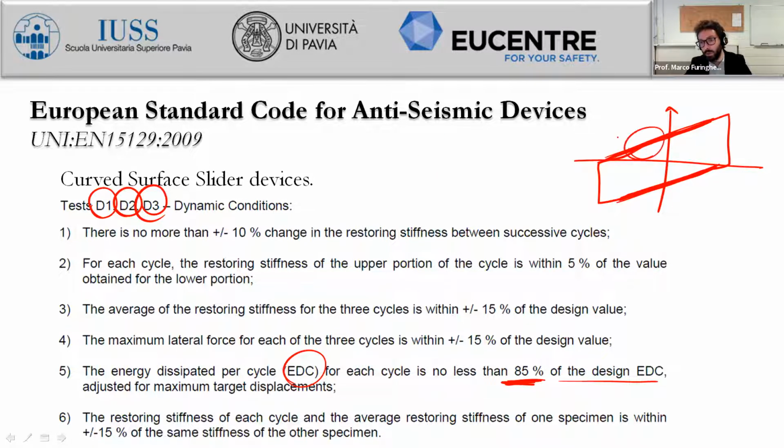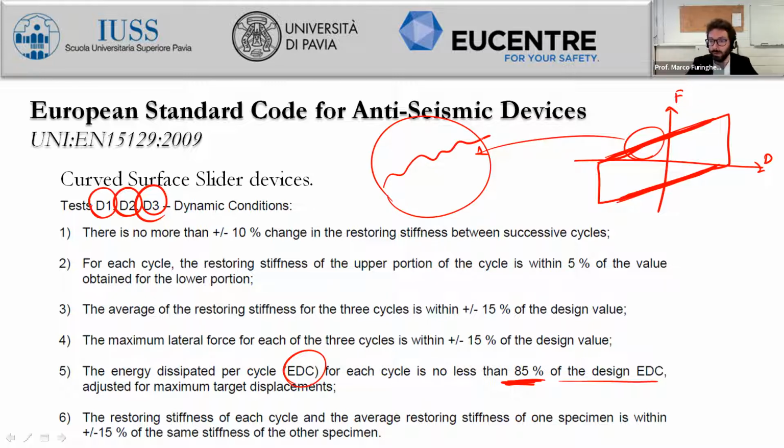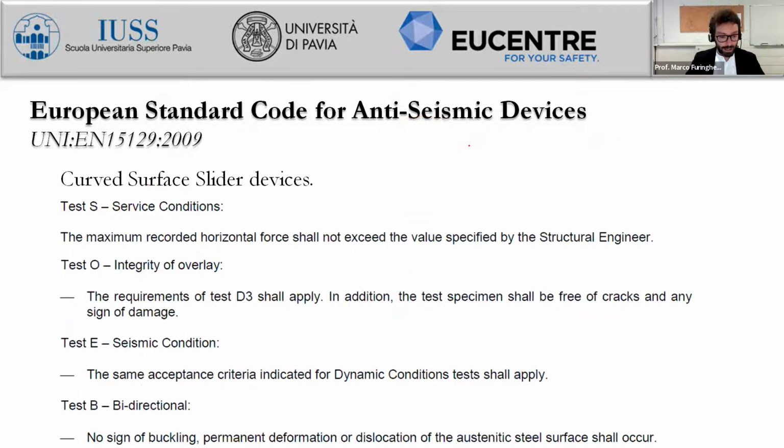if we want to zoom to this portion of the force displacement loop, we have something irregular, which is actually the recorded signal, and we want to model it like a linear branch. Okay, so we will be able to compute just a linear stiffness, which is just a line, according to a least square procedure. And there should be later on in the slides the definition.